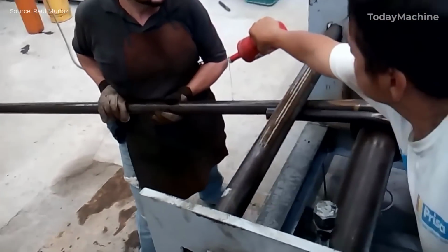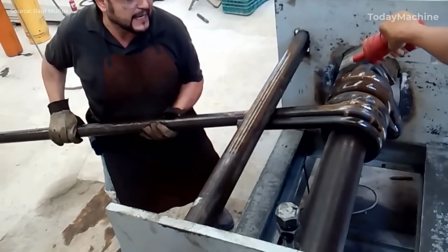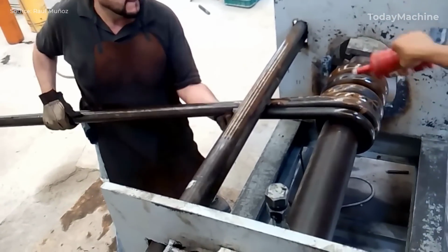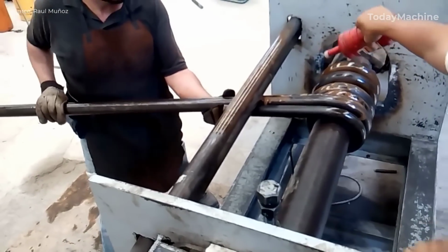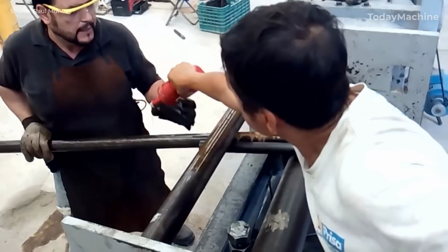Pitch, typically between 0.2 to 0.5, depending on the required spring index. Coiling speed, 20 to 30 revolutions per minute, RPM, to maintain control over the material and prevent work hardening during winding. Spring index. The ratio of coil diameter to wire diameter is usually maintained between 6 and 10 for optimal performance.